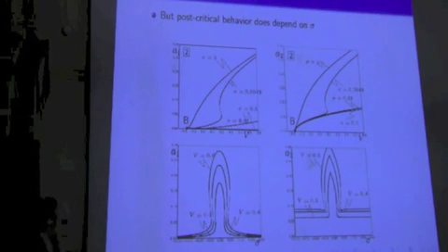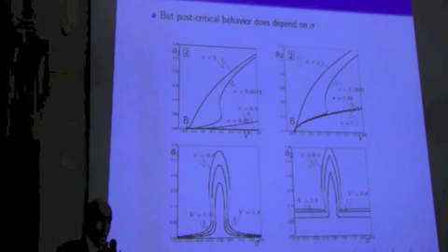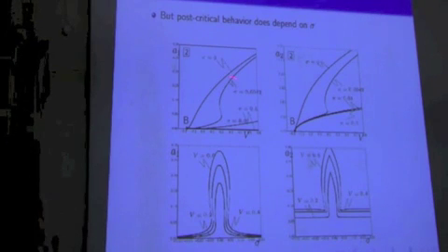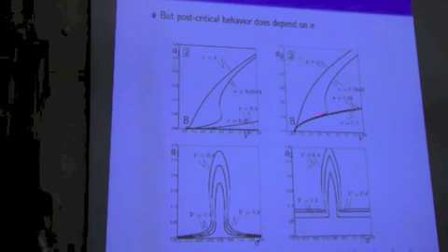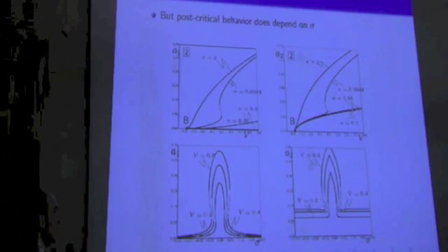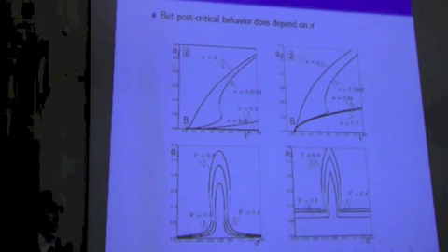It means that the two towers oscillate with periodic time law with the same frequency. If we increase the internal detuning, we get to a situation where one tower stops oscillating, or it's better to say it oscillates at higher order, while the second tower oscillates at these amplitudes, which is the typical behavior